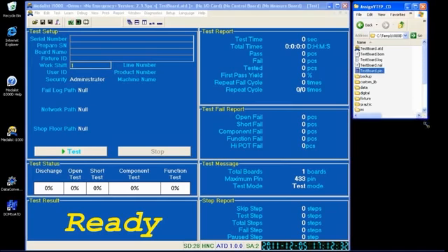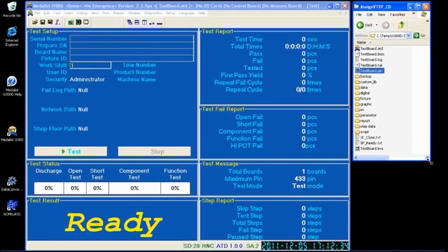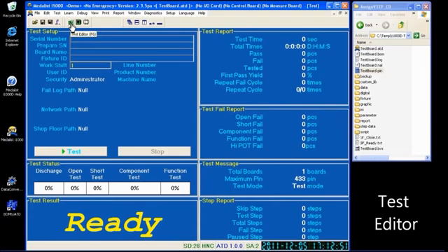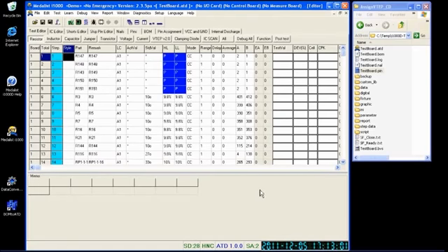At the same time, if you notice in your Windows Explorer, the software actually creates a lot of other folders within your ATD files directory itself. These are the default folders used by the software. Alright, so back on the i1000 interface, let's go into the test editor interface, where we will assign our tests for VTEP and clamping diode. Just click on the Test Editor button and get into the test editor interface over here.